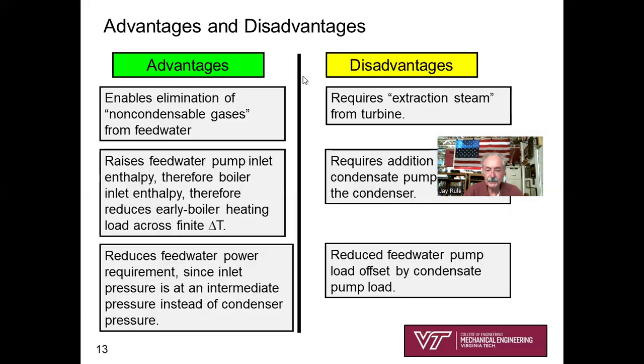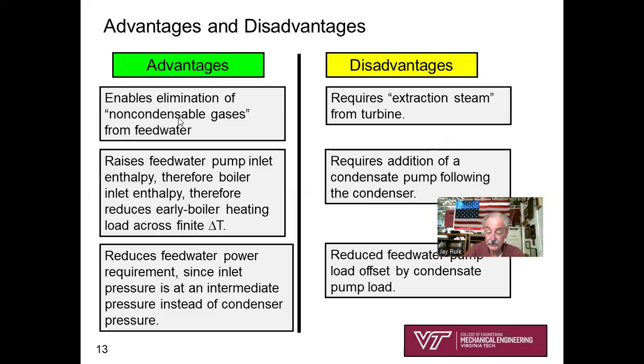Advantages and disadvantages of the open feed water heater. Great advantages: it enables elimination of non-condensable gases like air or oxygen that's dissolved in the H2O. Very powerful tool. Also, this open feed water heater raises the feed water pump inlet enthalpy, and therefore the boiler inlet enthalpy, if you think about your pump analysis.